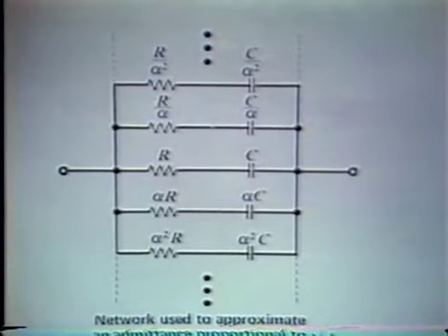The thing we're really interested in getting out of this network is 45 degrees of phase margin in our eventual system. In other words, we want the transfer admittance of that thing to have 45 degrees of actually positive phase shift. If you look at the actual phase shift associated with the transfer admittance, of course it ripples. When the transfer admittance is going as radical s, you have 90 degrees of phase shift or approaching 90 degrees of phase shift.